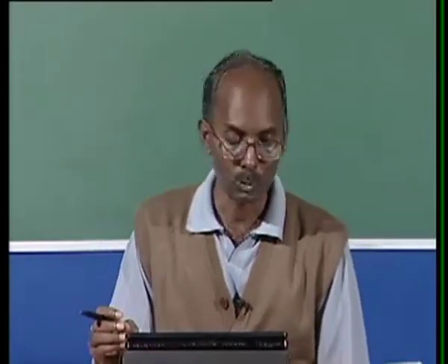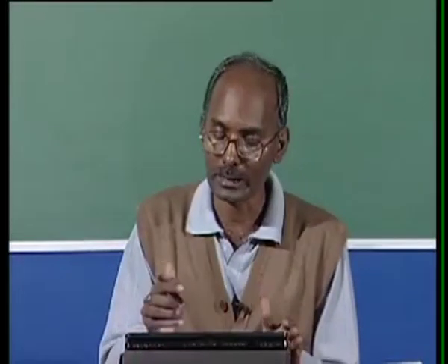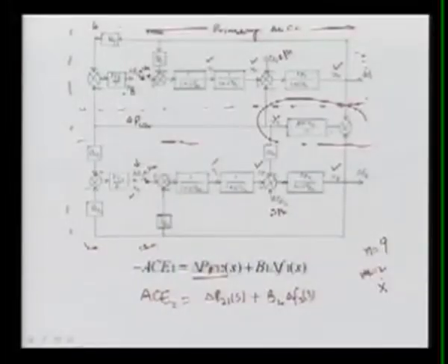So U1 will be the combination of all with different scaling factors, means different k gains. So we have to now write the state space form, and then we'll see how we are going to change. If you are taking input from all the states, then it is called full feedback. If you are connecting only x8 to U1, then it is not full feedback. So we have to now write the state space representation of this model.